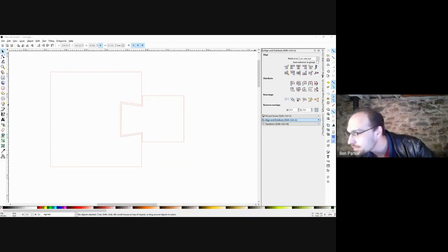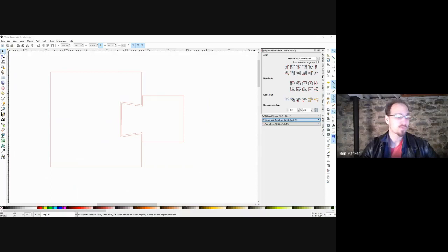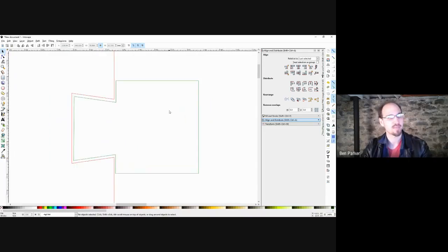Oh, hold on. Laser only cut all the lines. Good question, John. So you can cut, you can also engrave. So usually I reserve red for cutting and a green outline for engraving. What's going to happen here, as long as this is a bounded polygon or curve of some kind, it doesn't have to be straight edges.